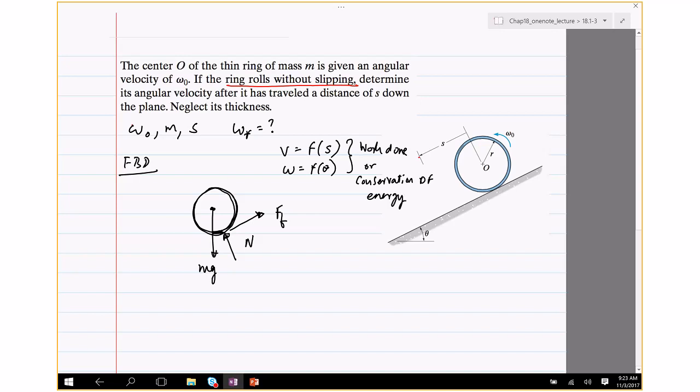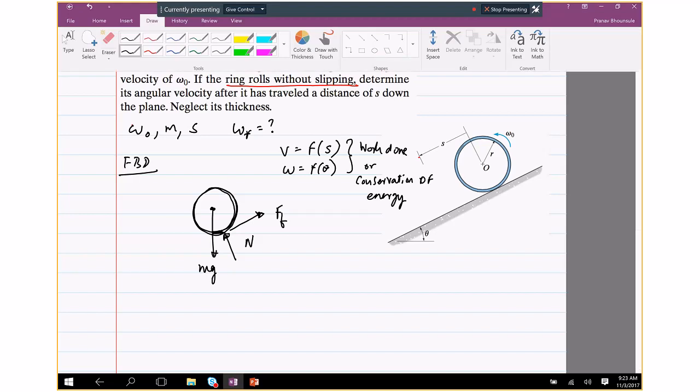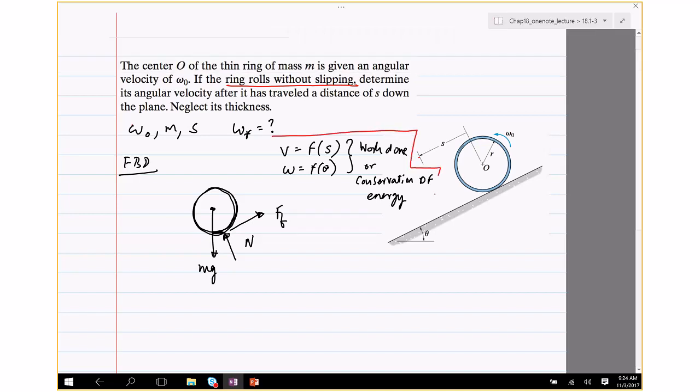We're going to see conservation of energy problems a little later in this section, but it makes your life easy if you use these principles when you're told to find v as a function of theta. But it's always true that F equals ma and moment equals I-G alpha plus r-G cross m a-G, the moment about whichever point, always works.